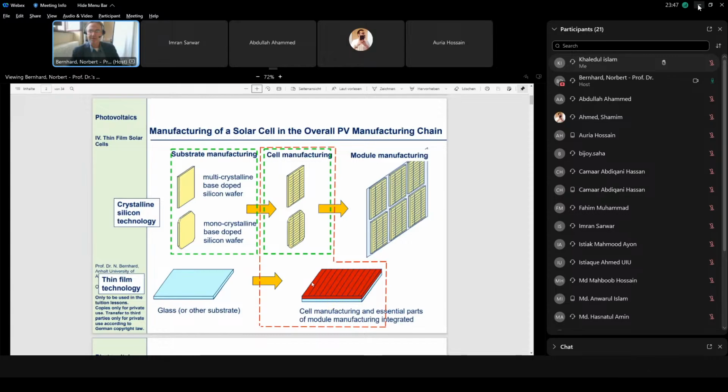Just opposite. You see, in the 2-6 cell, we start with the metal back contact, then we have the semiconductor, and then we have the TCO. And the top side is the light incident side, and here it's opposite. That means here we first deposit the TCO, then the semiconductors, and then the contact.